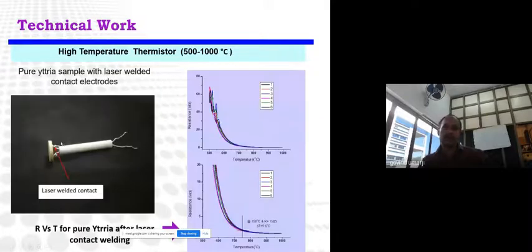One more point is the interconnection. We observed that when we laser soldered the platinum electrode to the platinum wire and did the repeatability study, we got a delta T variation of 5.6 degrees. That means it improved the repeatability when we had a proper contact with the electrode.